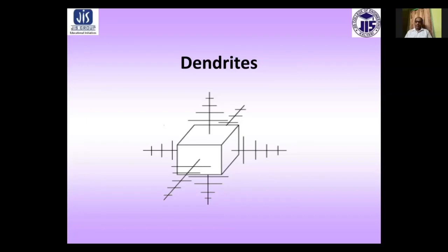In a perpendicular direction, the liquid region will have a lower temperature. Since there has been no crystallization and consequently no heat evolution, the crystal will grow in a new direction, that is from point A to point C, until heat is dissipated from the initial region of crystal growth.